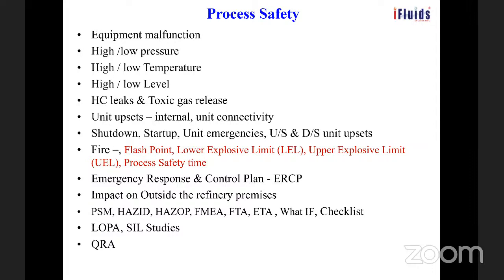Sir, what is the FCCU flow path? FCC flow path: you get the feed, it is heated up to about 470 to 500 degree temperature and enters the reactor. In the reactor, the cracking takes place, and after cracking, the cracked hydrocarbon enters the fractionator, and there it is getting distilled. It's a distillation column, a fractional distillation column.